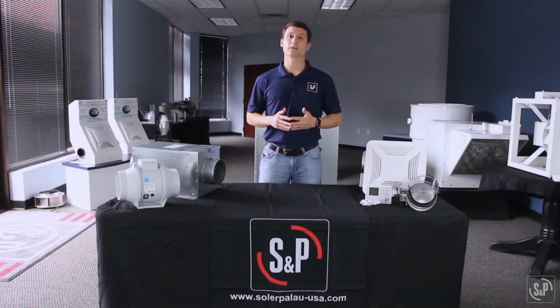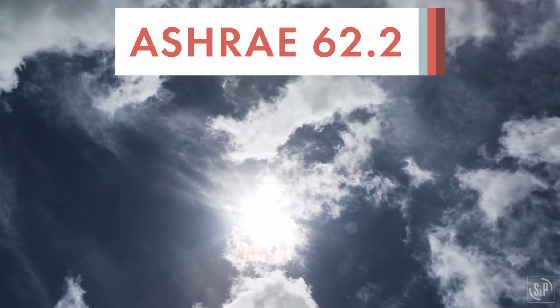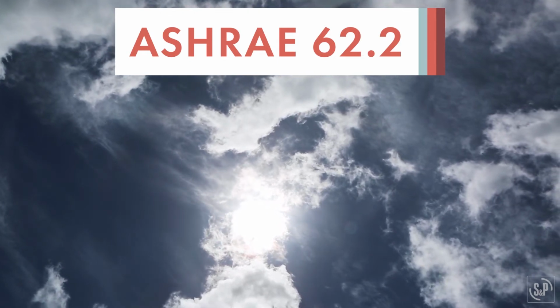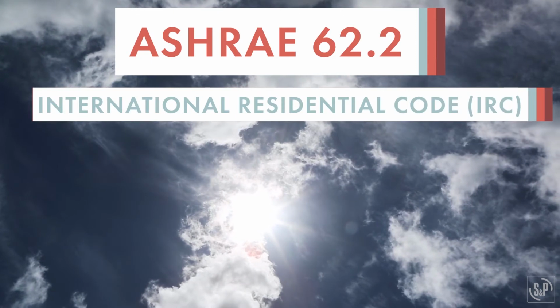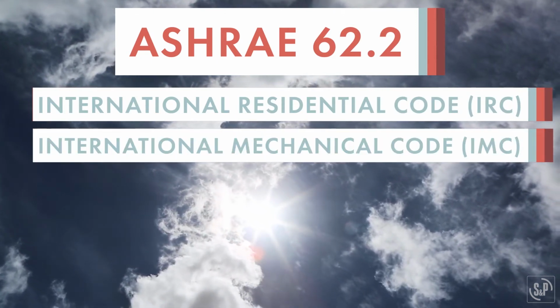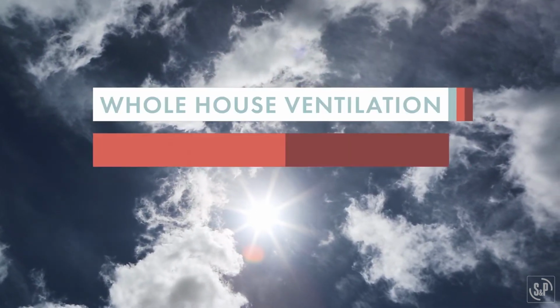Let's take a look at some of the codes and standards that regulate indoor air quality. The ASHRAE 62.2 standard sets the minimum requirements for mechanical ventilation systems to provide acceptable IAQ in residential buildings. Building codes such as the International Residential Code and International Mechanical Code amend and reference these requirements to ensure occupant health. There are two basic requirements: whole house ventilation and local exhaust.